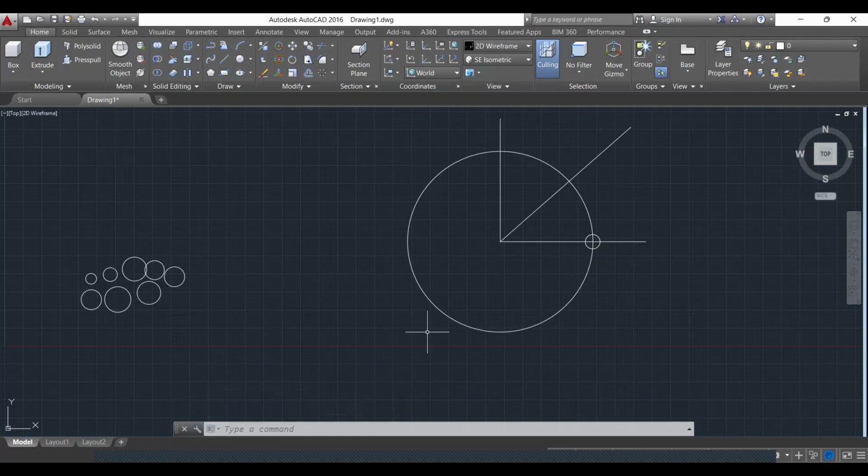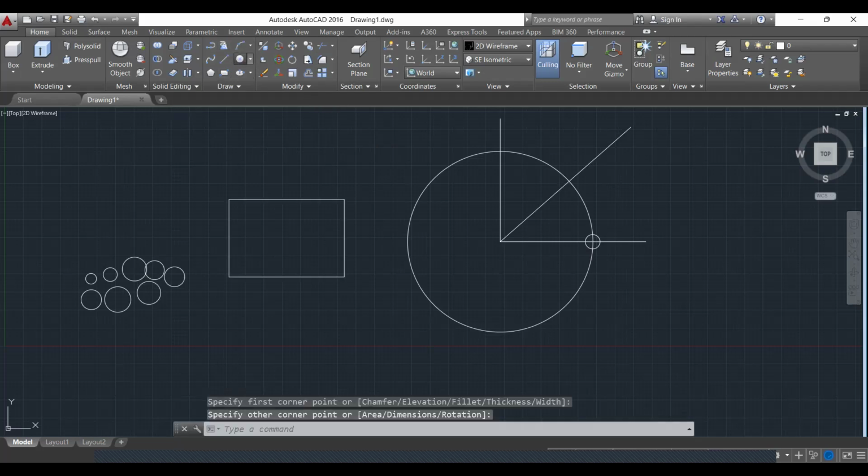So that you don't need to stretch much more on everything, right? Okay. So that's the uses of the array, right? The rectangular array too. It's when you have a rectangle like this. Let's say it doesn't only apply to circles. You can use rectangles too, or circles in a rectangle. Assuming I want you to fill the entire space over here, I just come and select my rectangular array. Select it like this, press enter. You see, it has filled everything, the whole box.